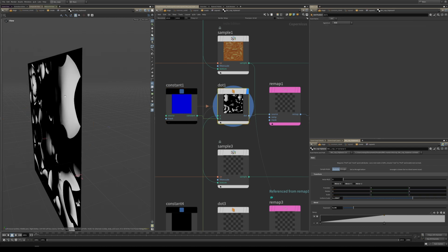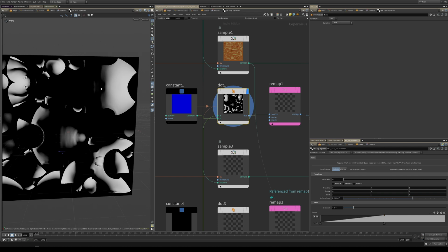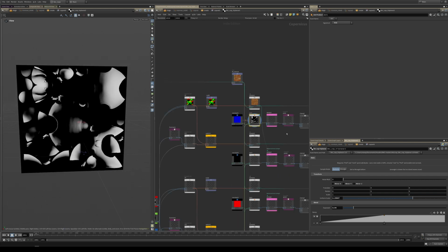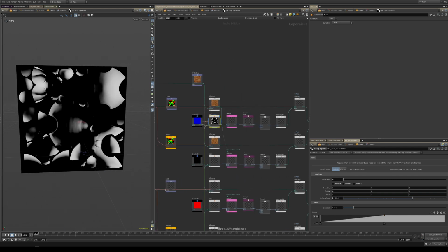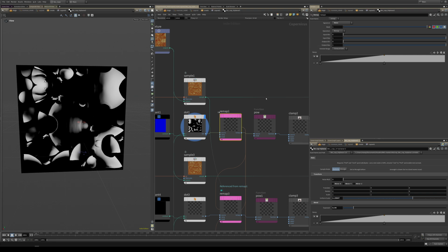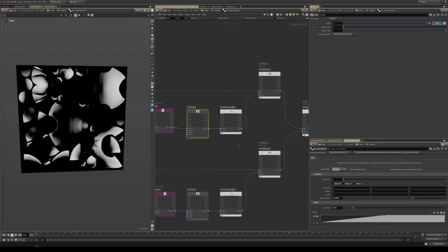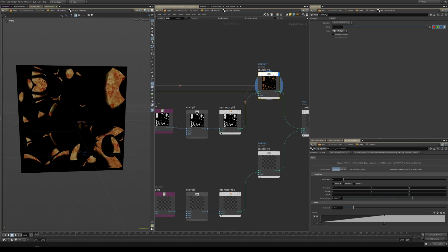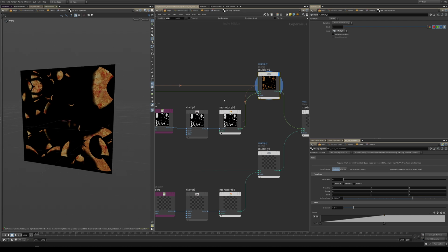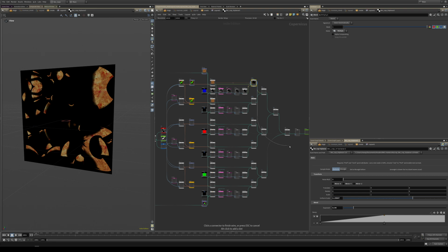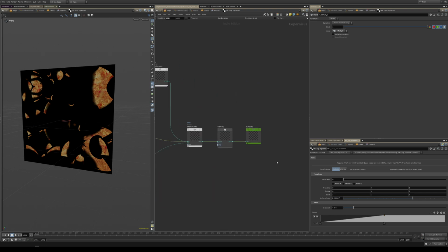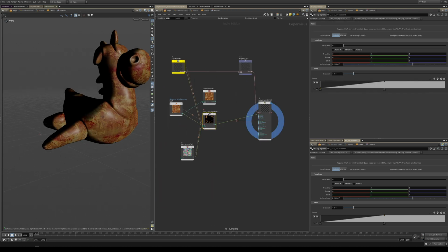We dot product, that gives us this, which we can use as a mask for this projection over here. So there's a remap to clamp it, there's a power, that's our exponent, another clamp again, and then we make it from mono to RGB, and we multiply this over our texture. If we plug this in here, we can now see what's going on.